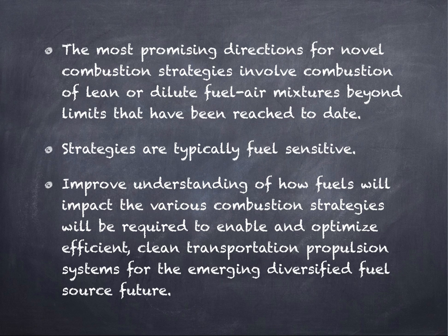The most promising directions for novel combustion strategies for high efficiency, clean ICEs and GTs involve combustion of lean or dilute fuel-air mixtures beyond limits that have been reached to date. In general, the new combustion strategies require operating near poorly understood limits of combustion stability and/or at conditions for which the combustion reaction zone development in IC engines and stabilization in GTs are not understood. A major additional complication is that these strategies are typically fuel sensitive.